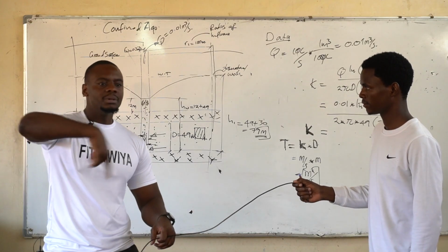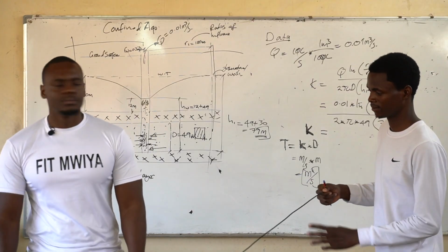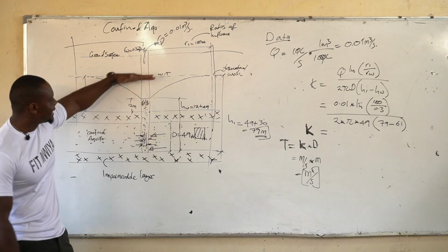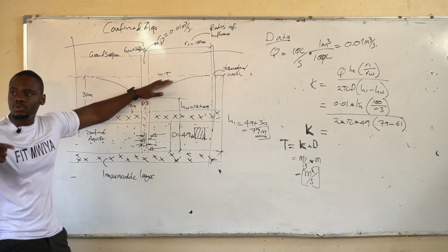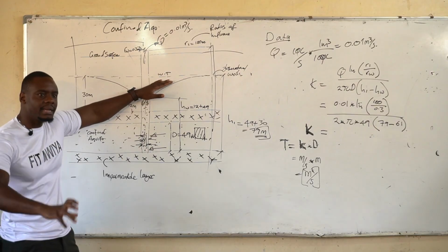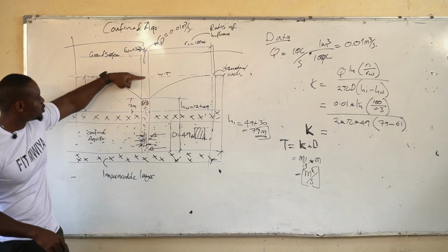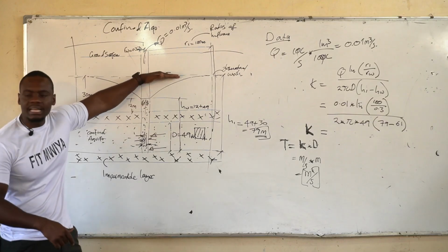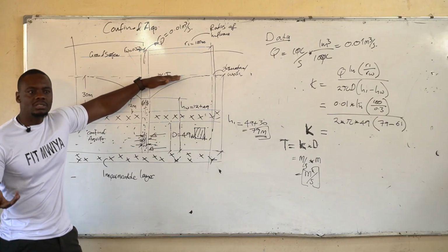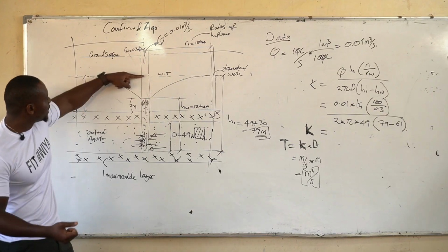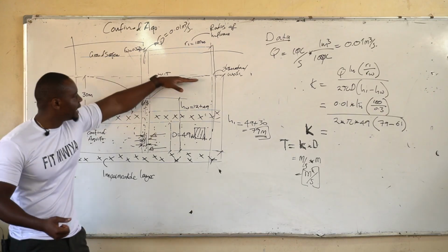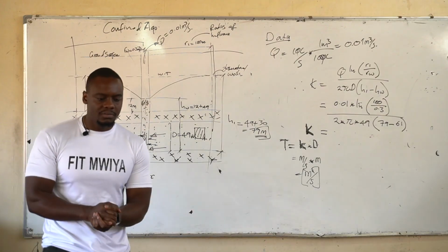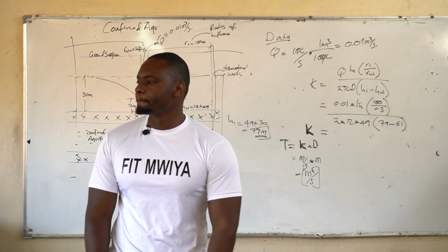But then imagine it being circular. This is what's happening here. Originally it's here before you pump, but as you pump day by day, steadily, it begins to drop. But it can't just make a sudden drop here and maintain the line here. That is not realistic. So when it begins to drop, because it's one line, it drags along with it the other sides of the soils.